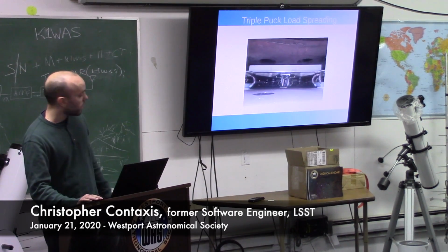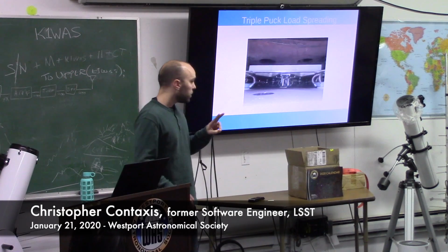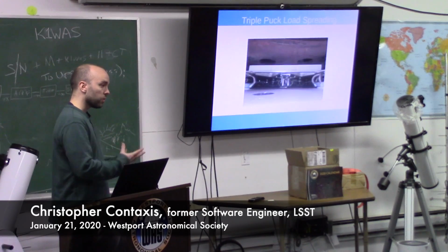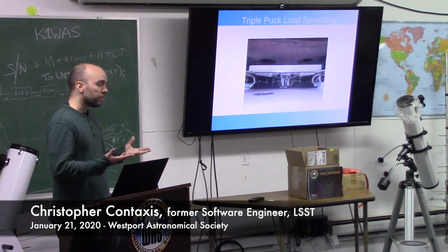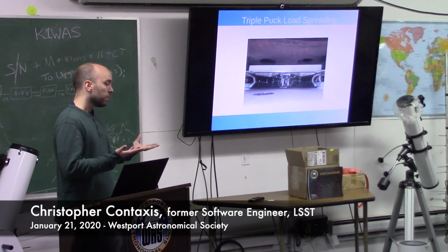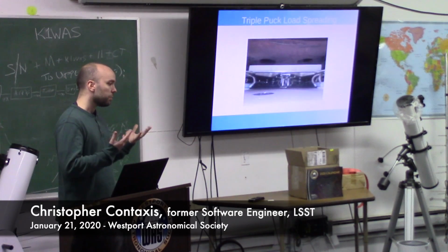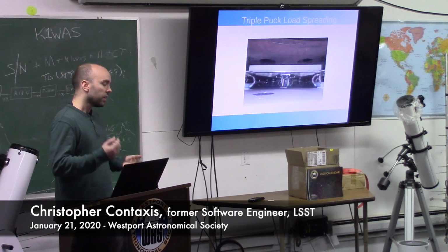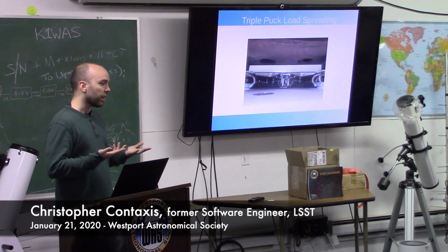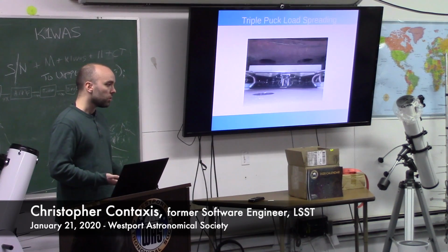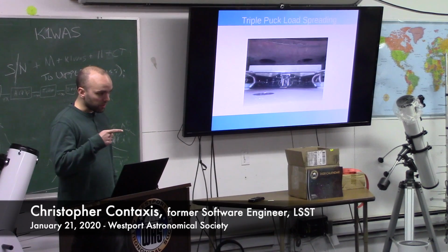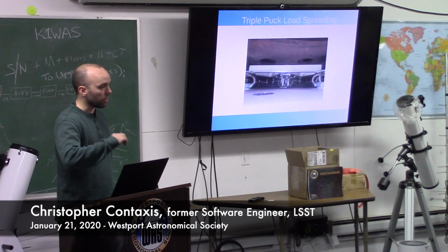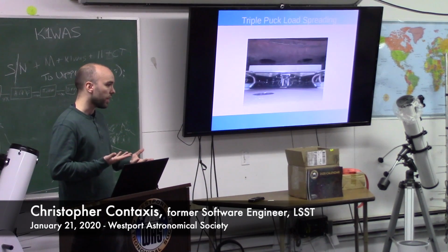That comes later. And then what you're seeing here is you have two different types of actuators. One set is responsible for lifting the mirror. So they handle lifting that 18-ton mirror up. But they have no stiffness. So if you just lift it up and you have nothing to define the position of the mirror, the mirror is just going to go all over the place. It's essentially floating, so you could also think of it like air hockey. You could take your finger and poke it like an air hockey puck, and the mirror would move. You can move it wherever because its weight is fully supported by those actuators.